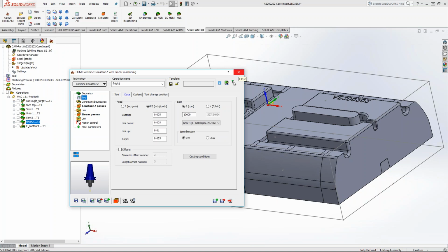Have you ever tried using your CNC machine to polish? I actually did that, and this was a long time ago. I did that with a little cavity that was some kind of hand poured rubber, and actually did some burnishing on a D2 that was hardened to 60 Rockwell.